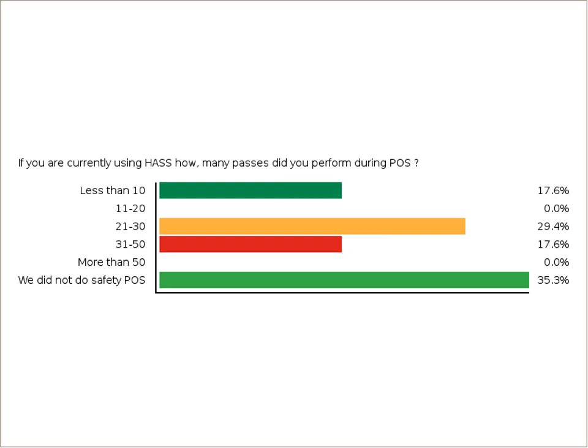Since then, I've heard reports of people running good product for 100 times or more and not seeing failures. Typically what you find is if you've got a new failure, it fails very quickly in HASS, or a new failure mode will show up very quickly. So if you have good product, it will tolerate many, many passes through this screen.